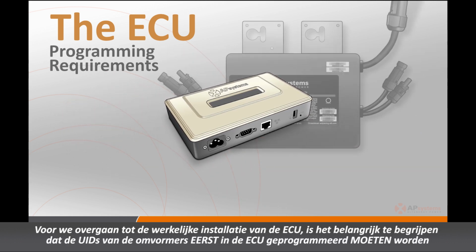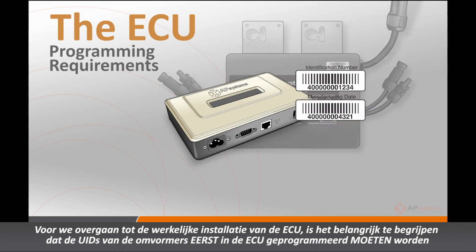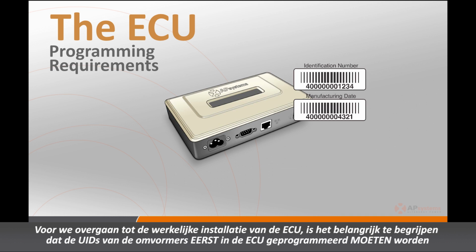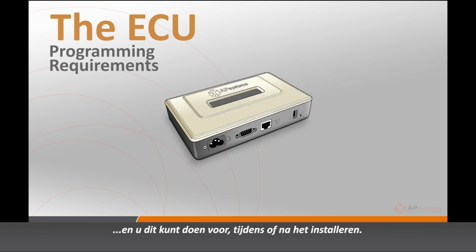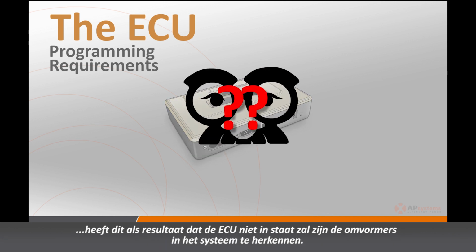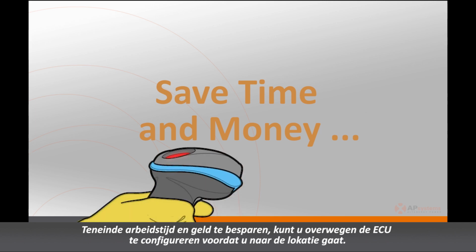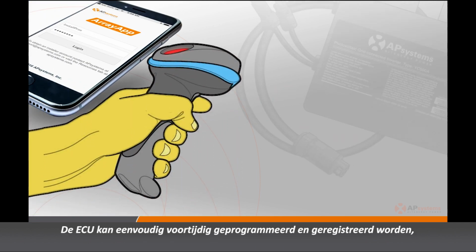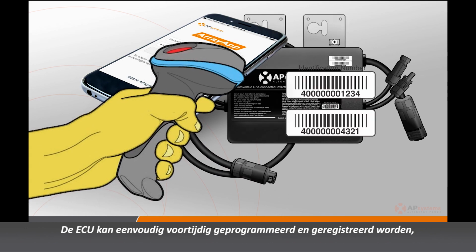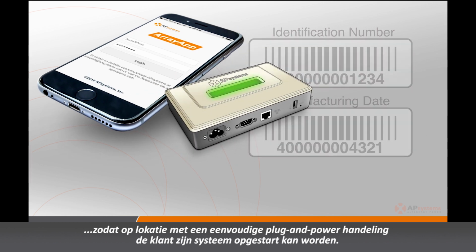Before jumping into the actual installation of the ECU, it's important to understand that the ECUs must be programmed with the inverter UIDs, and this can be done before, during, or after the installation. Failing to perform this part of the overall installation process will result in the ECU not being able to recognize the system's inverters. To save installation time and money, consider configuring the ECU before you head to the job site. The ECU can be easily pre-configured and registered in advance, ensuring simple plug and power operation on site as the customer's system is energized.